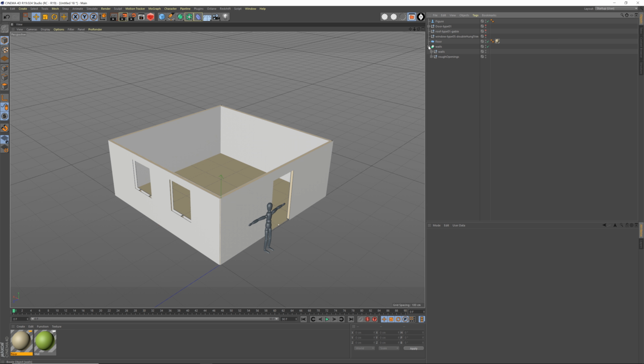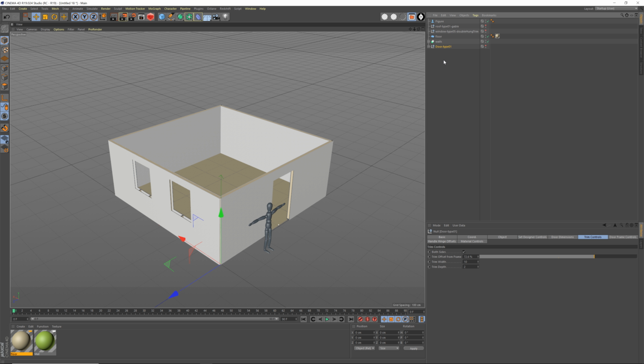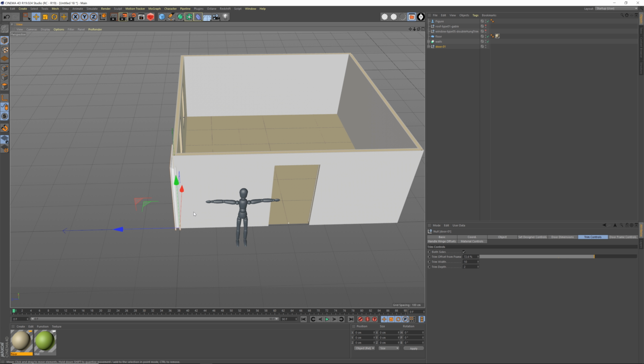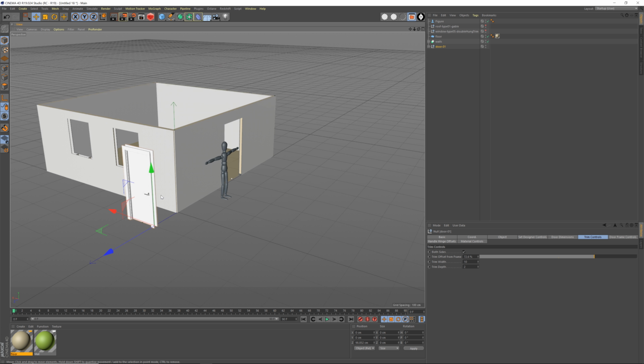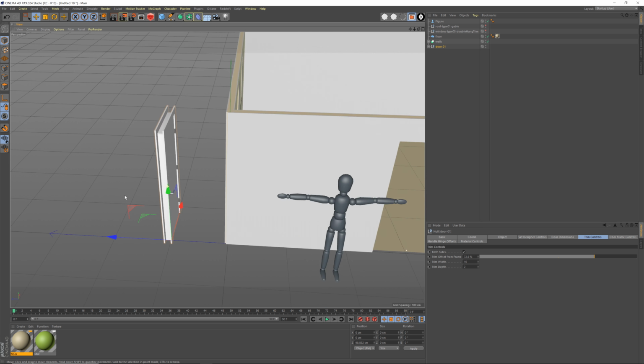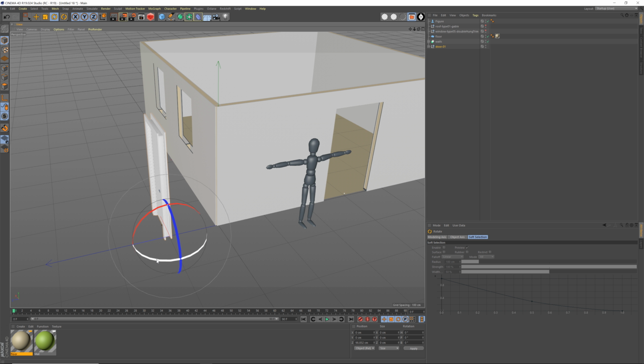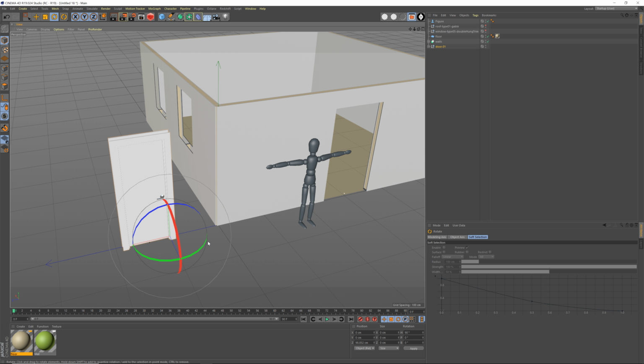But now let's keep moving here. We're going to go to our door type 1, which I'm going to rename to just door 1, and I'm going to unhide it. So there's our door, and we're going to add this door. It's right here. We're going to add it just like you would add a real pre-hung door to a real rough opening in a wall. So I'm going to spin it, holding shift, hit E, and I'm just going to slide it over here.